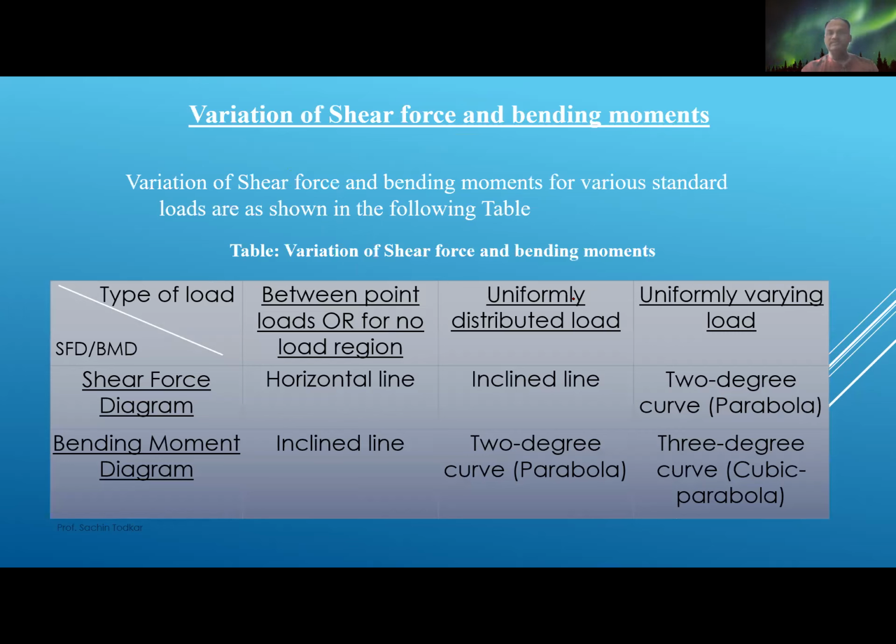Now, this table is very important because lots of questions have been asked in your online exam on this variation of shear force and bending moment. So, shear force diagram between point loads or no load region, shear force diagram is horizontal. If the loading is UDL, uniformly distributed load, SFD will be an inclined line.